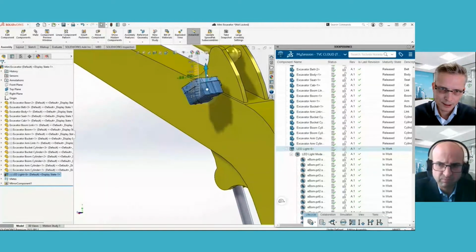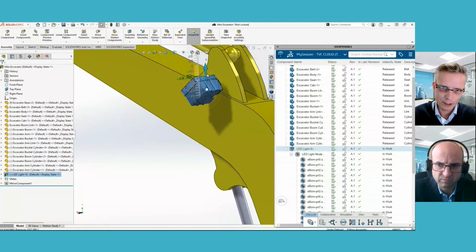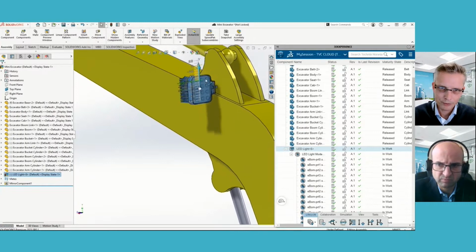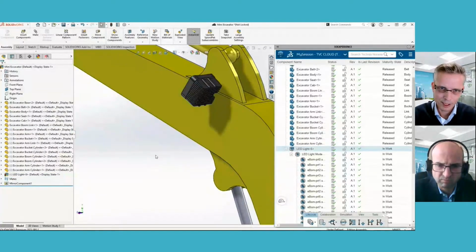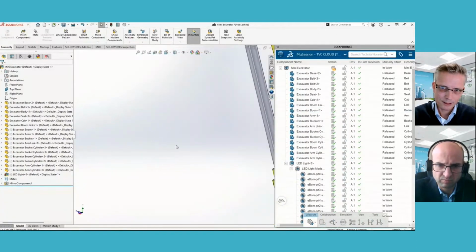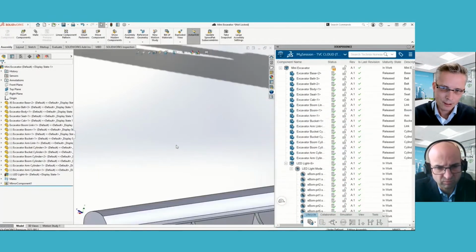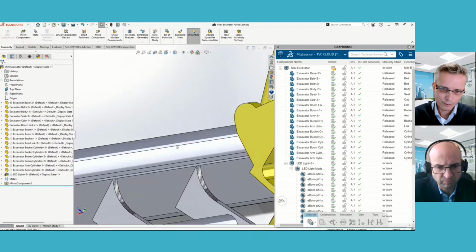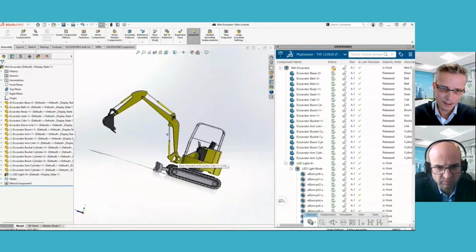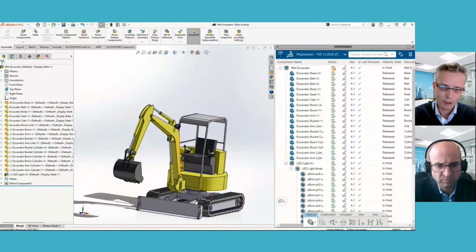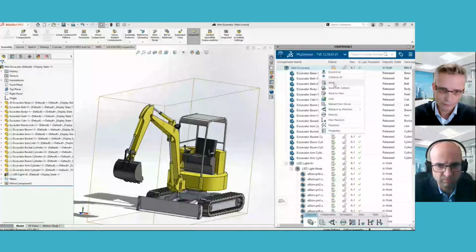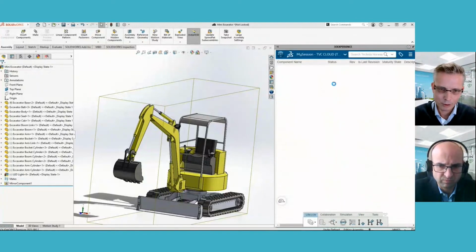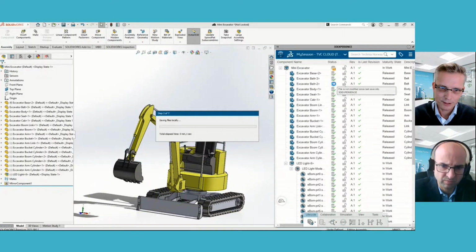In many cases, since this is a purchased component, you would only like to care about the assembly level when sending this information to ERP, but that can be configured if you want all levels of the bill of material or only the levels that you are building in-house to be transferred. Those are flags that can be set as part of the integration to 3DEXPERIENCE.